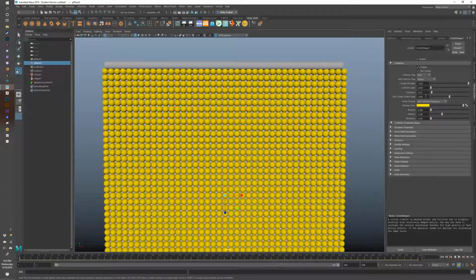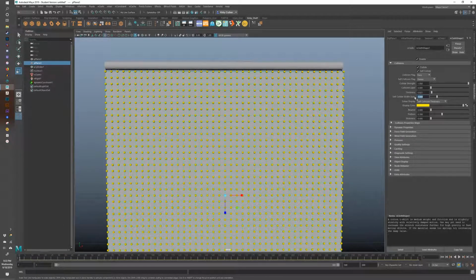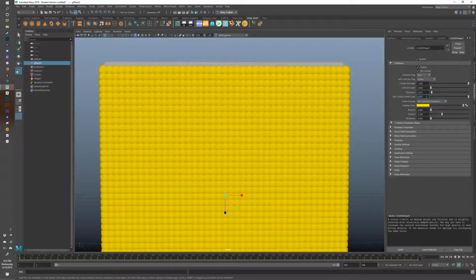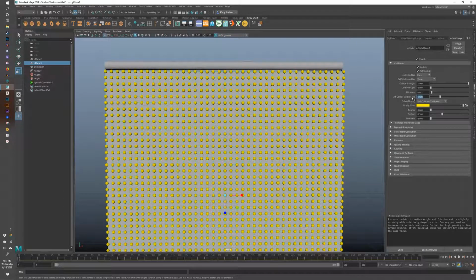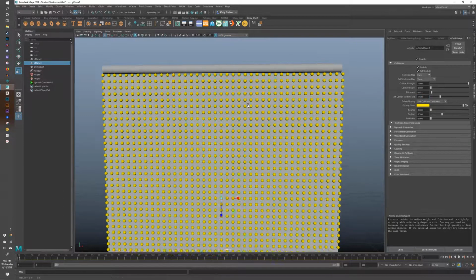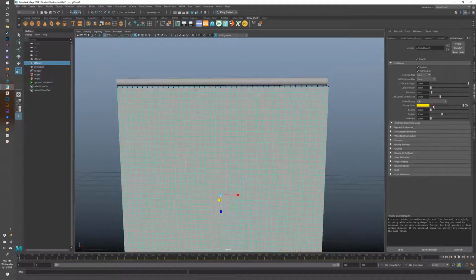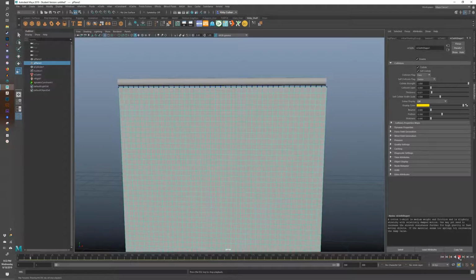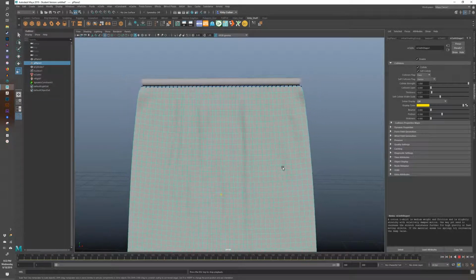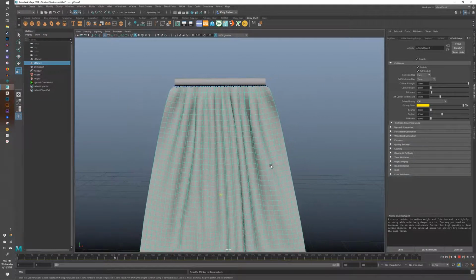So the self-collide scale, I'm going to actually shift down to maybe 1.5. Oh, not 6. 1.5. That way they have a little bit of room to kind of move in on each other. So turn that off, and I'll rerun the simulation and see if the cloth is a little bit better.